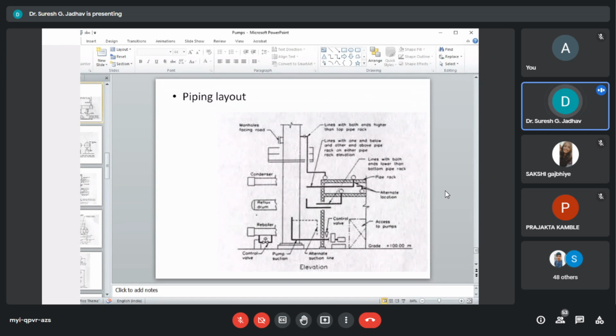The horizontal elevation after the line leaves the vertical run is governed by the elevation of the main pipe rack. The lines to run up further to the rack can approach the rack at higher elevation considering the size of other horizontal lines and be placed on the top tier. These can turn left or right depending upon the plant overall arrangement.